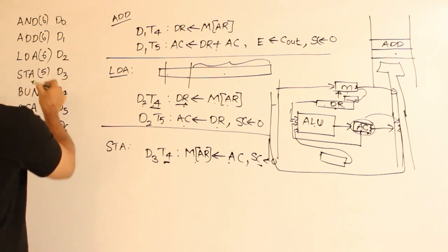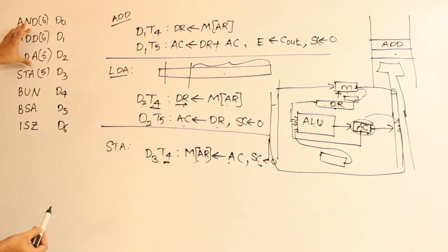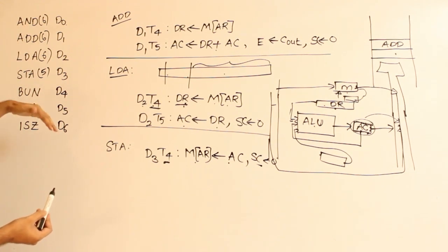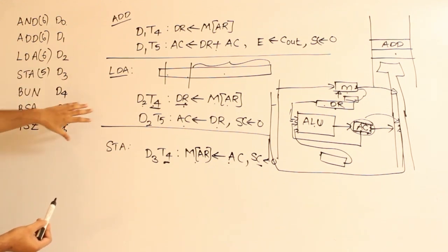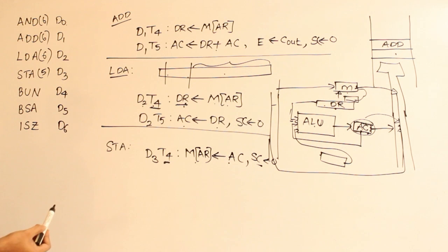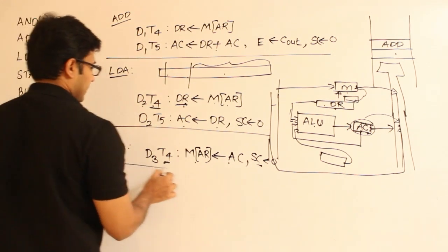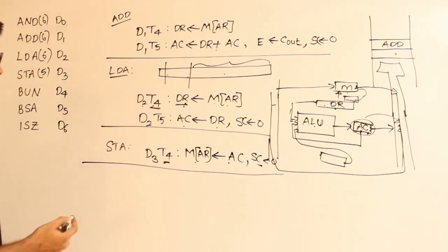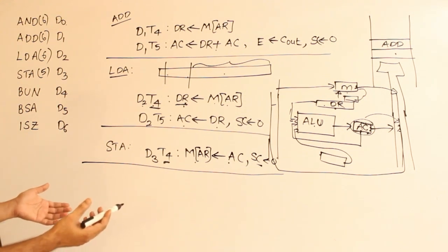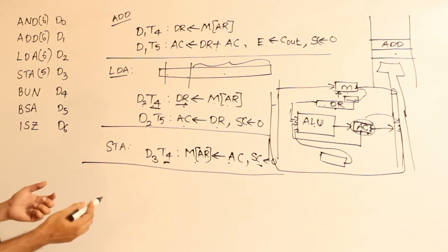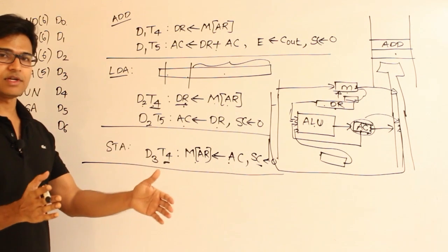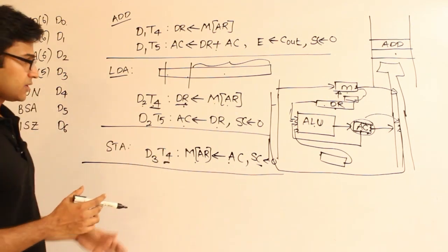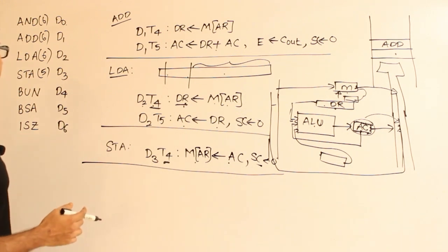So if you observe it, that is the reason each instruction will take a different number of clocks depending on what type of instruction it is. Got it? Some instructions might be fast, some might be slow, depending on the operations that we have to perform here, right? Why are we focusing on this so much? We have some questions where they will say that add is going to take these many clocks, multiplication is going to take these many clocks. Then you might feel, why should every instruction take a different number of clock cycles if all the instructions are of 2 words or the same size? Because internally this is the working, so we need different clocks.